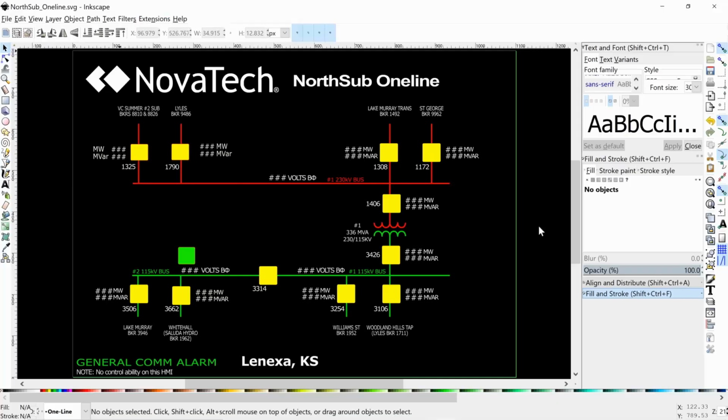One of the questions came in of like, how can we minimize the amount of rework here, and how can we just basically build template files and then reuse those from one project to the next? And so I'll go over a few little details here. So one thing as Eob kind of touched on is basically we have a bunch of yellow rectangles and/or breakers, if you will. And the idea is that if we create something visually speaking, and we forget to apply the programming behaviors to it, it's going to show up as that yellow indicator, and it's going to tell us on the HMI screen that, yes, we missed the programming.